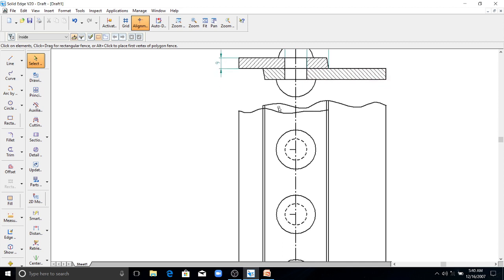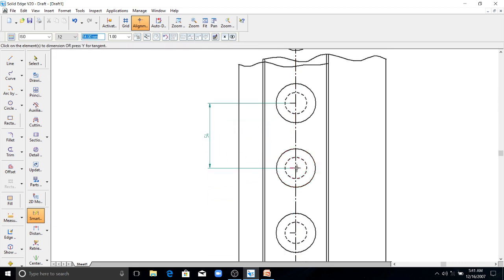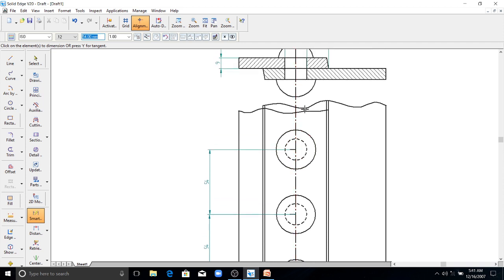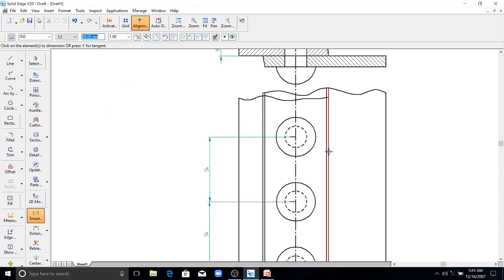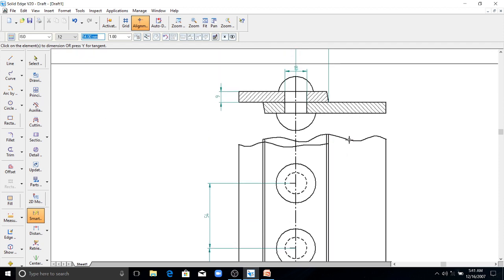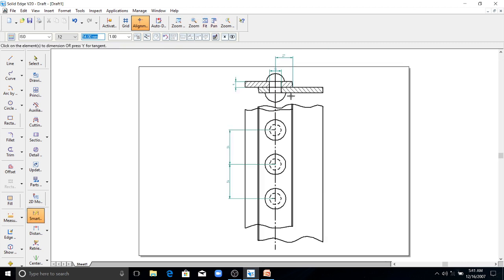So next pitch P, that is 54 mm, 3 times the diameter. That distance is 54 mm from here to here, 54 mm. Similarly, from here to here is 54 mm. So this completes the single riveted lap joint with the 3 rivets. You can see here.